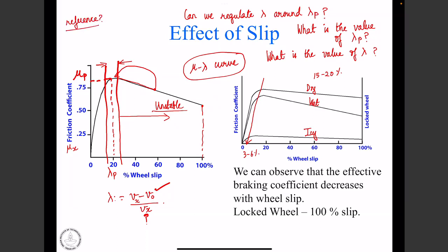Now, when we come into the room, let's say the actual temperature is some 32 degrees Celsius. That is the actual value. We measure it using some temperature sensor. Then what do we do? We compare the reference value and the actual value, and then we take corrective action by blowing in cold air, right? And progressively the actual temperature reaches the reference, and the air conditioner adjusts its output accordingly. Okay, so that's how the AC will work.